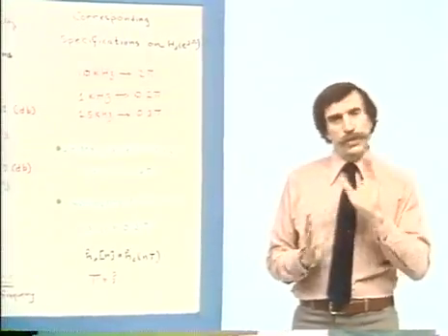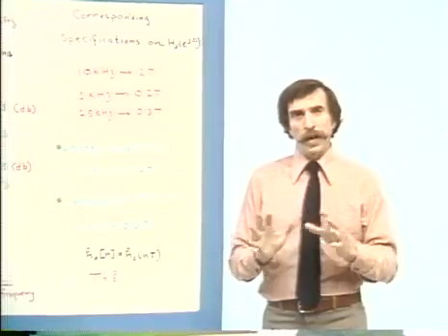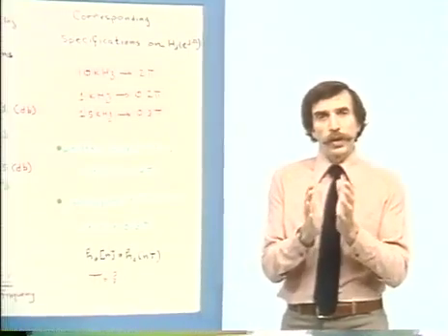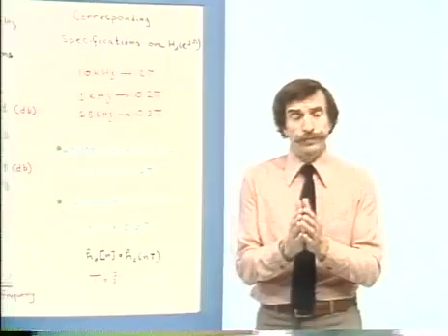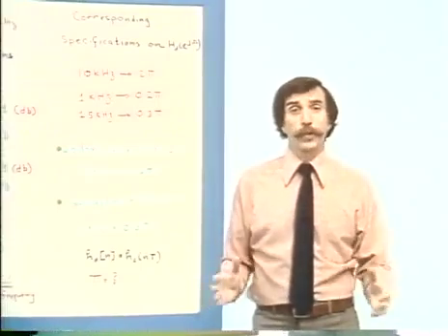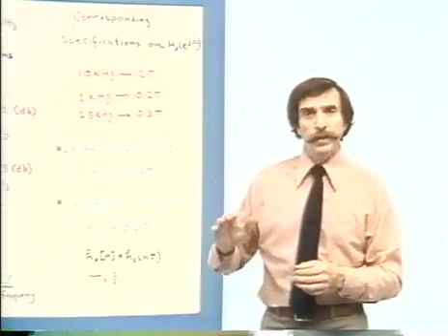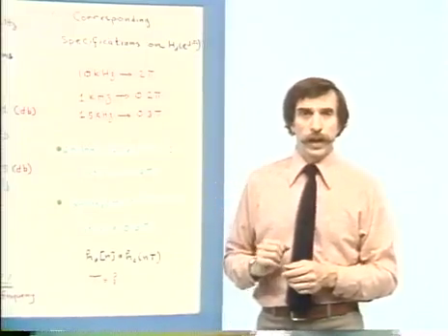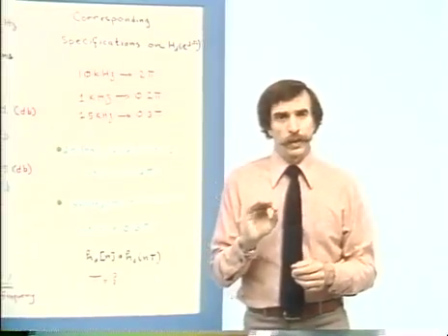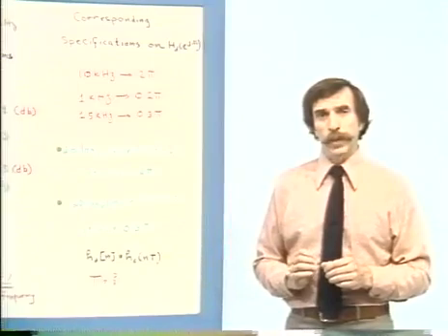Now, this is a fairly subtle, complicated, tongue-twisting issue, but the essential point is that the parameter capital T that we use in impulse invariant design is a totally different, unrelated, and in fact, as it turns out, arbitrary parameter, which is not necessarily pegged to the sampling frequency. And I think it would be difficult for me to totally clarify that during the lecture. It's discussed more in the book, and certainly you should take plenty of time to reflect on it.